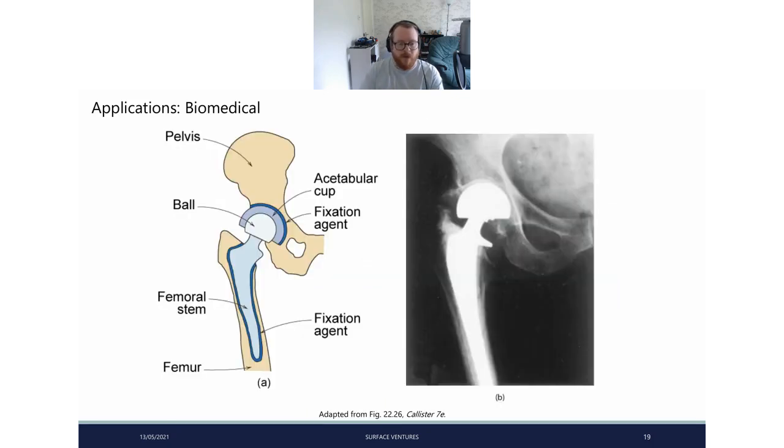Okay, so here we have a nice diagram of hip implants. So in addition to the actual titanium itself, there's a few different things. So looking at metal on metal, hip implants are quite bad because of the amount of wear debris generated, and you're releasing a lot of metal ions into your body. So things like the ball material and acetabular cup are chosen out of different materials.